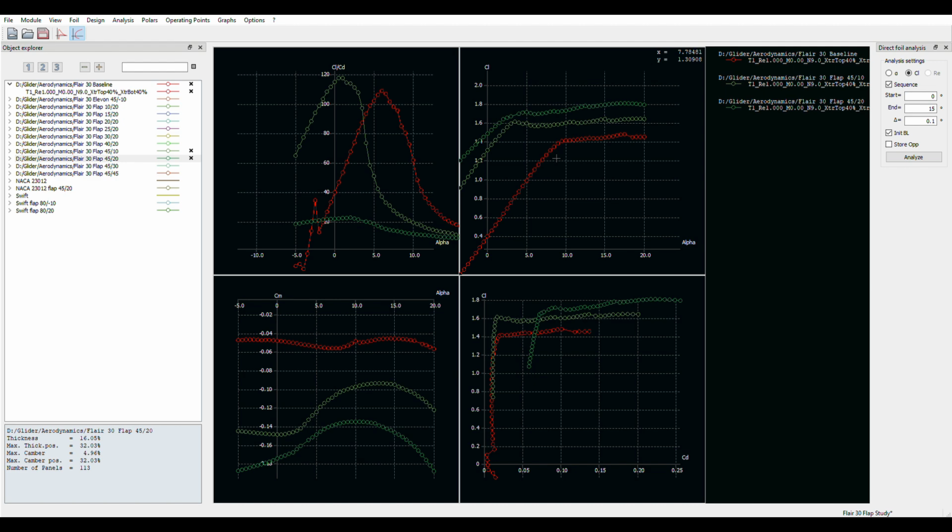That's okay. You could fly like that all day. You'd be fine. He's heavier. He has to fly at a higher speed. He wants to get back. He wants to get that 40 kilometers per hour or less. So he puts out 10 degrees of flap. Well, now the airfoil is operating way over here. He goes from here to over here.